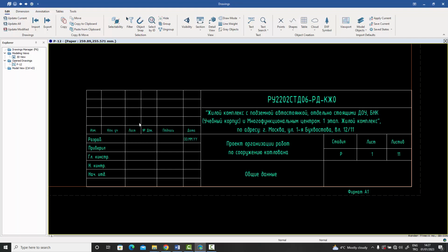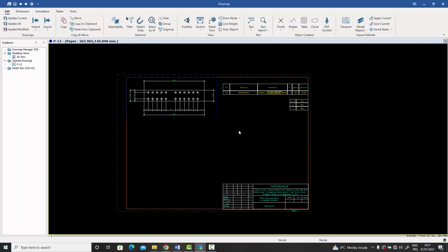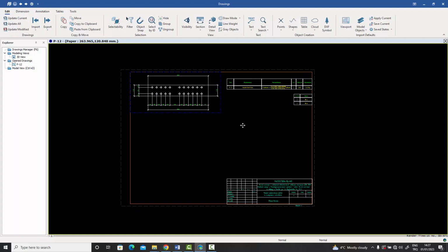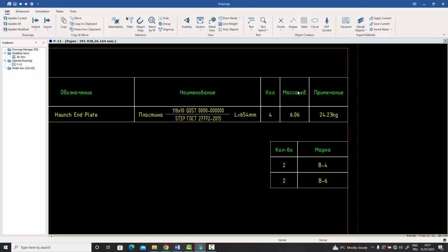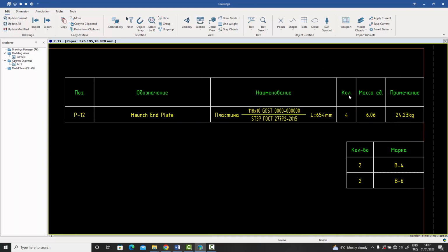And we have the capabilities, I'm not going to show them over here, of including signatures as well as all the customized information which we have in the title block. So this is very convenient. All you need to do is just create your model, and once you've created your model, you do the numbering, and you just right click on any part, and the part drawing will be created, as you've seen, directly off the shelf without any customization being needed.